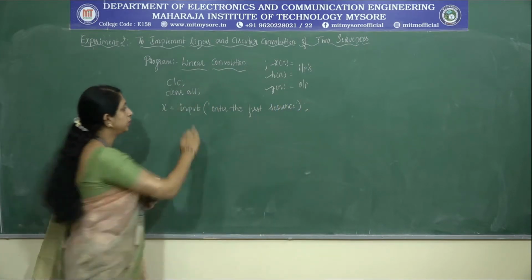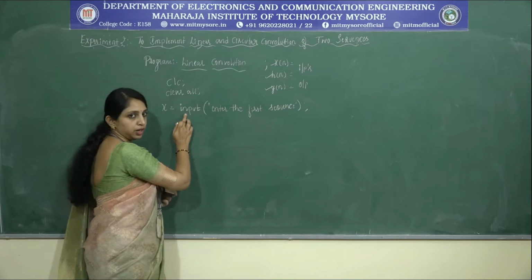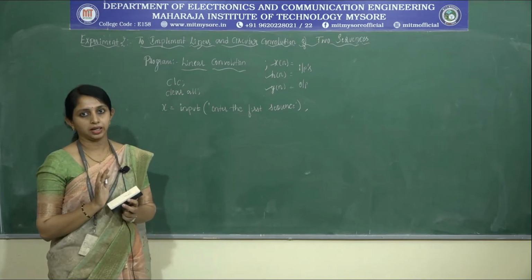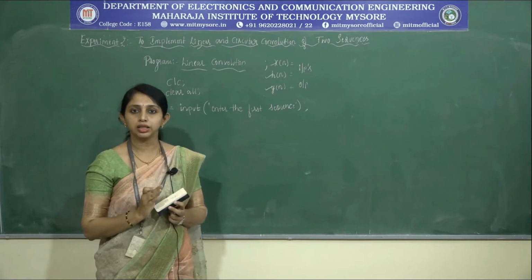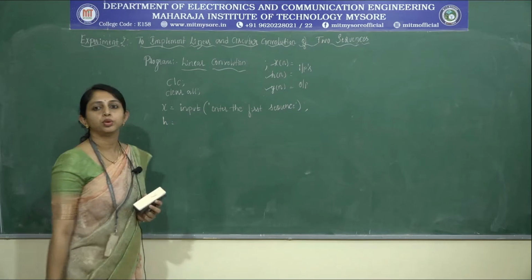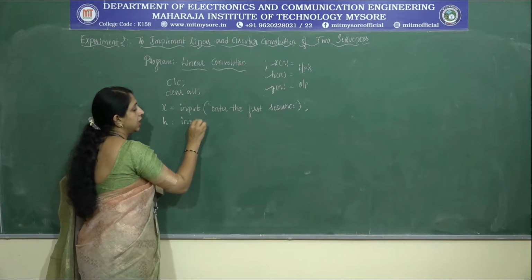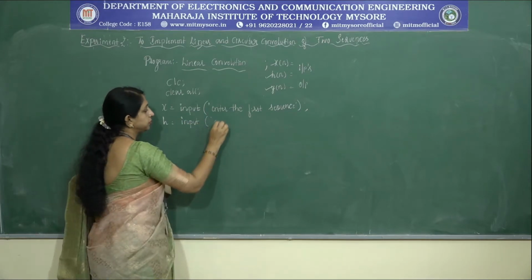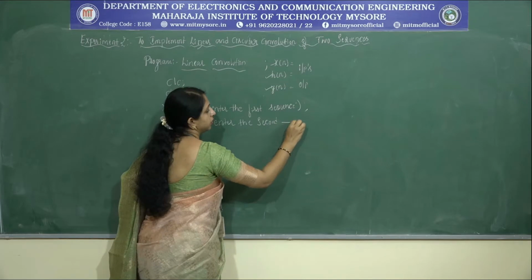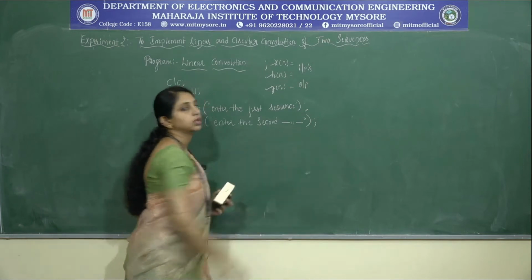Okay, so through the input you can enter the first sequence, or else you can also avoid this input function. You can directly enter the sequence 1, 2, 3, 4 like that within a square bracket. So preferably try to enter the input through this input function of Matlab. Then we have a second input of linear convolution. It is H, and again I'll write the next line as input. Enter the second sequence. Close the single inverted comma and give the semicolon.